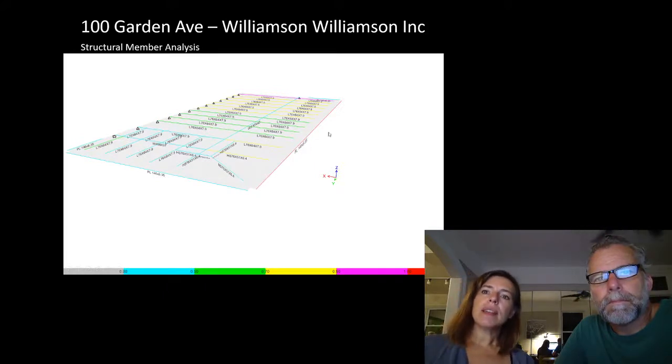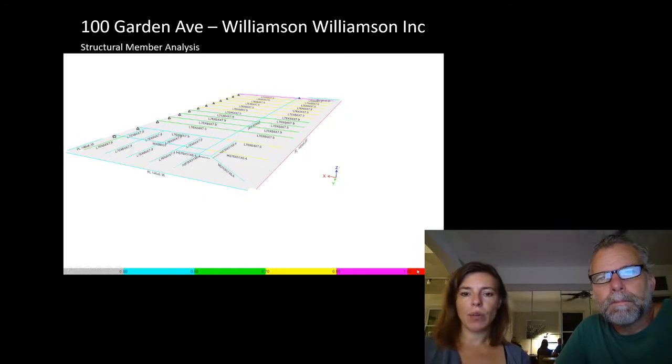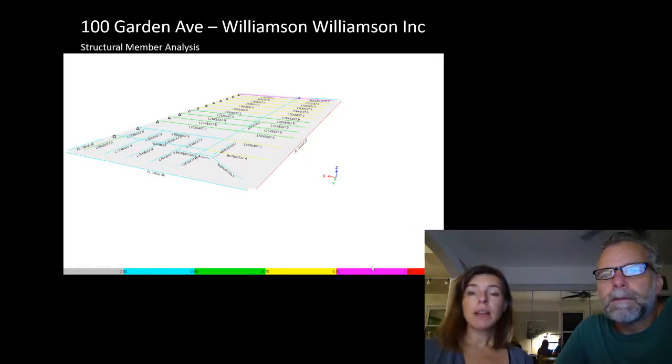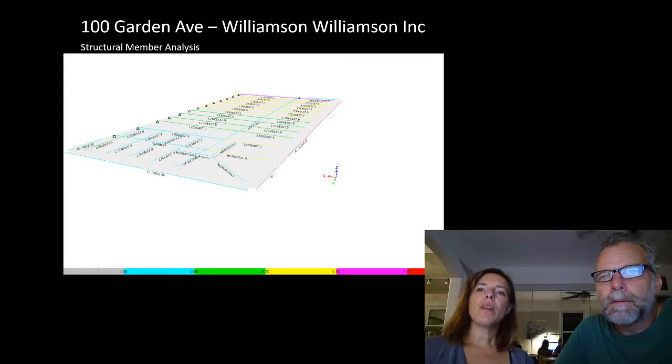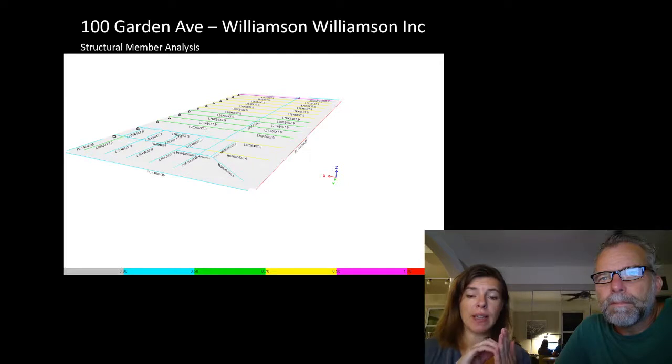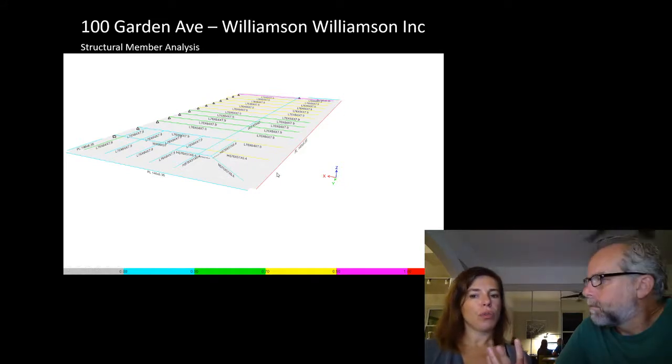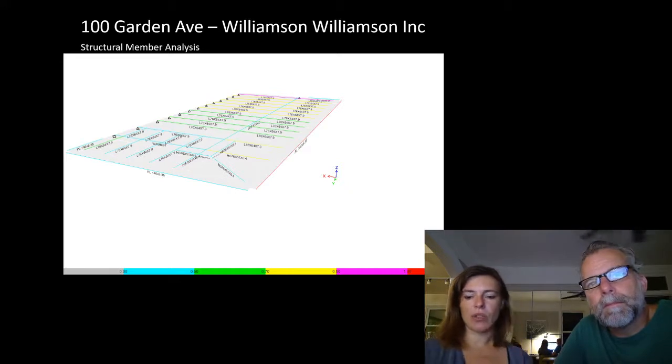You can see here that this says it fails, that it's over the strength capacity, or our factored load is greater than our reduced capacity. But if you look at this, when I go into that, I'm able to make the engineering judgment that it's not actually a failure in our overall system. It's modeled in there to help with the stiffness out at the tip of this canopy. So even though it shows it's overstressed, it's not something that I'm concerned about.